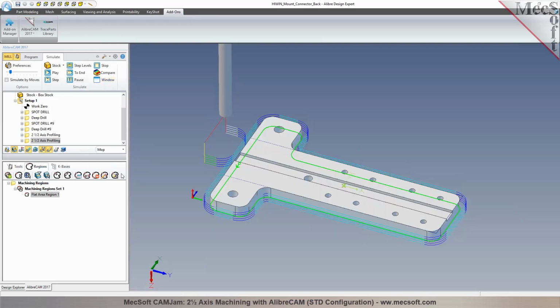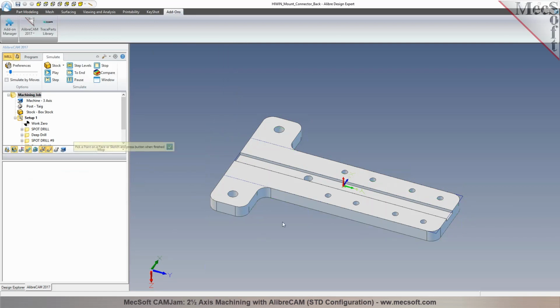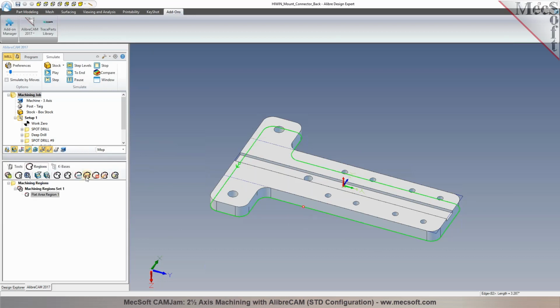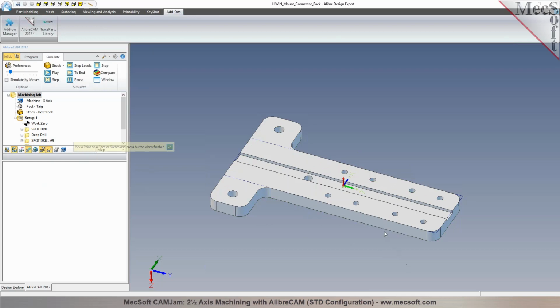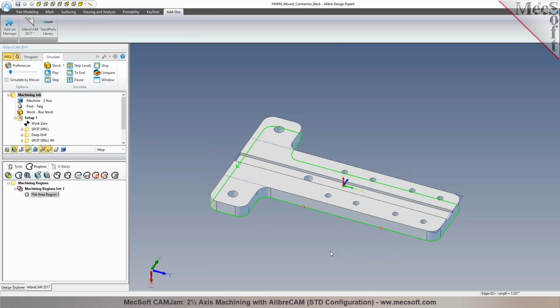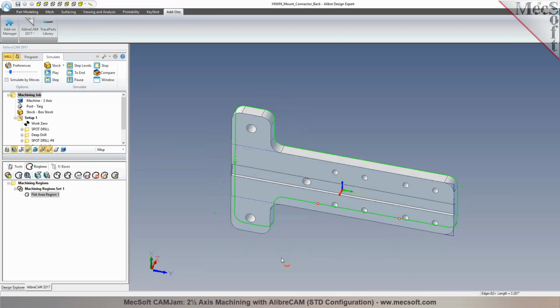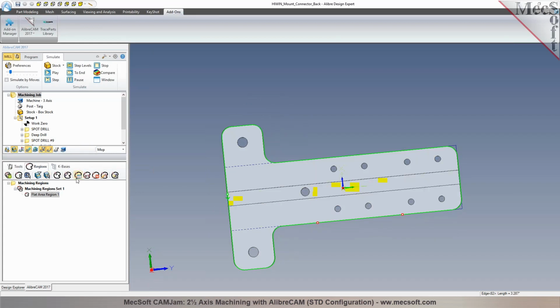So the way we would do it is, again, we go back to this predefined region that we created in here, and I can use automatic bridge points, or I can do manual bridge points, and this would allow me to pick bridge point locations. I can pick one over here. I can go back and do the same thing. I can pick one over here. So I have 2 bridge points defined. I can repeat the same over here for the other side as well.